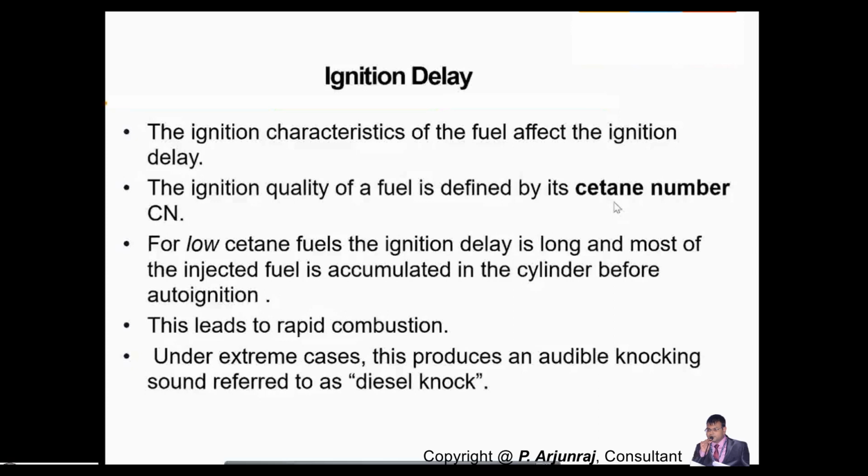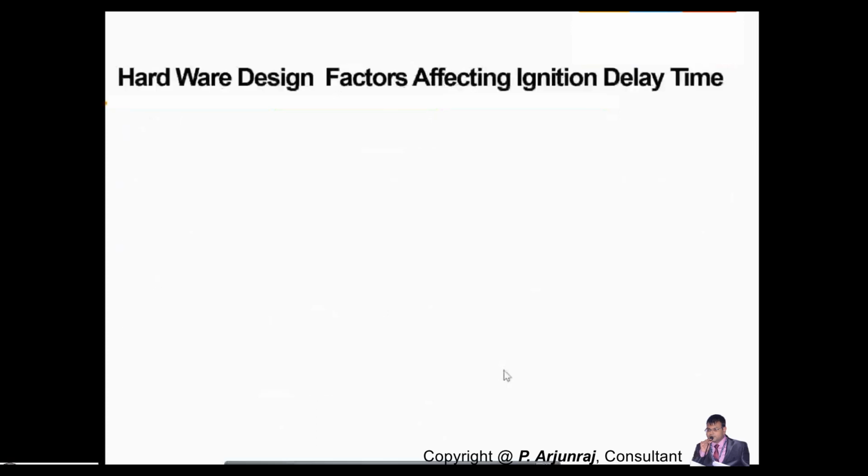So what happens when you have more ignition delay? This may accumulate more fuel in the cylinder before auto ignition, or self ignition, takes place, which will also lead to abnormal rapid combustion. Again, this also leads to knocking. I told you knocking is less affected in the case of diesel than gasoline, but still you can get diesel knock. That will happen only under extreme cases. But if you reduce the ignition delay, it is not going to happen.